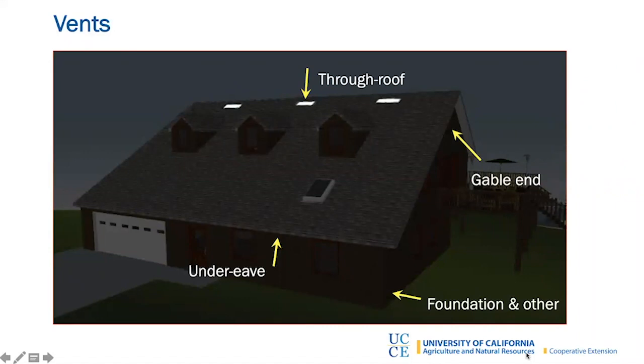So when we're talking about vents, typically vents are there from a moisture management perspective. It just so happens that embers can enter into the attic space or crawl space through these vents, and so we want to make the vents work as a moisture management tool and not be such a problem from an ember entry perspective or a flame entry perspective. So this vent has to do two things. It has to allow air for moisture management and not allow embers or flames, so that it doesn't provide a vulnerable spot to your home from a wildfire perspective.